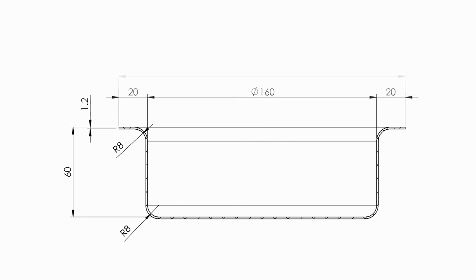Second, even if you have a 3D model of the final product, you still need 2D drawings because the 3D model doesn't contain dimensional tolerance. And for tooling and fixture design, the dimensional tolerance and GD&T are very crucial. But in our case, the tolerance doesn't matter, it's just a container.